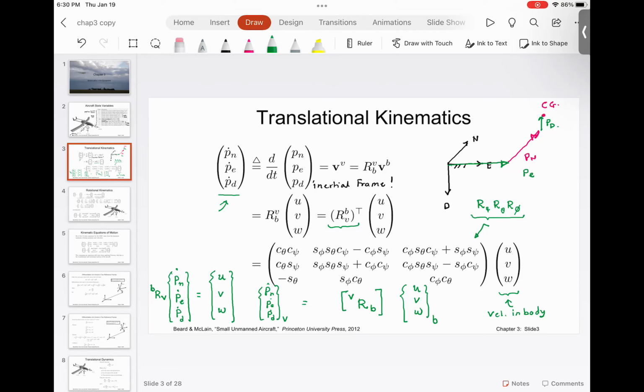And let me clarify once again what that means, because this point is actually very important. You have an aircraft. For a minute, just imagine you don't have any GPS signal. What you have is accelerometers in 3 directions, X, Y, and Z. They are going to measure accelerations. Accelerations are going to be noisy. Imagine you do very good filtering and you try to get rid of the noise. You integrate the acceleration once. You integrate the acceleration twice. So now what you have is the position.